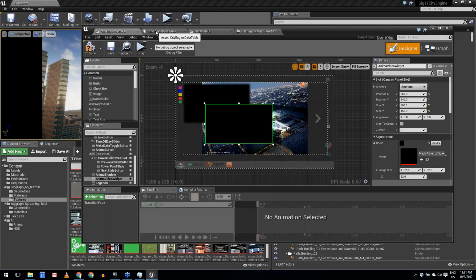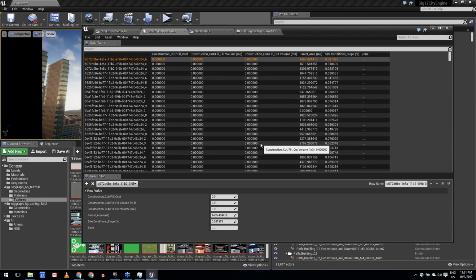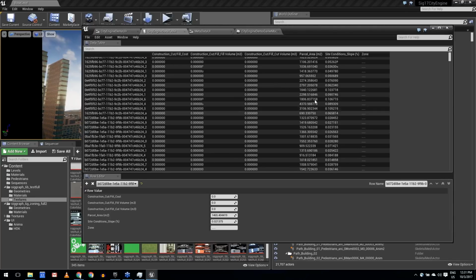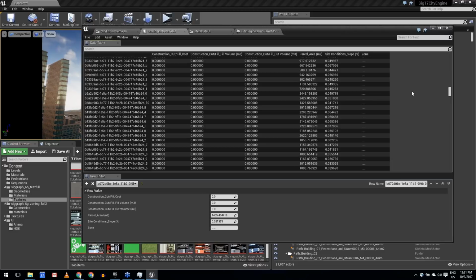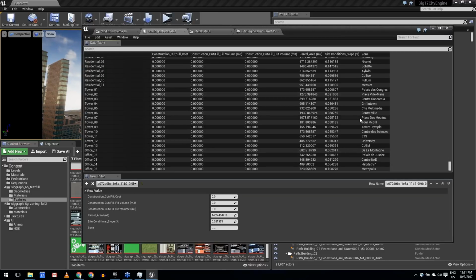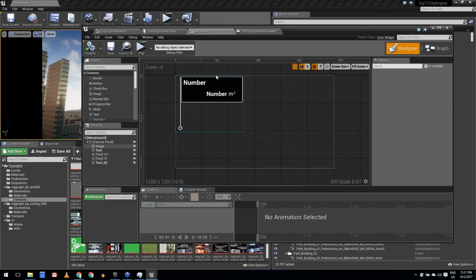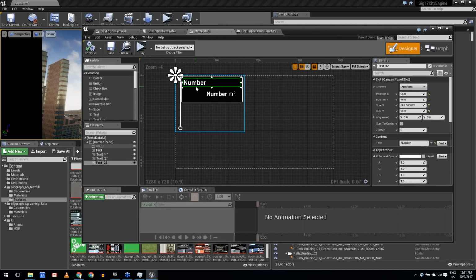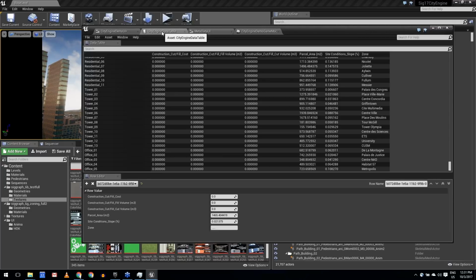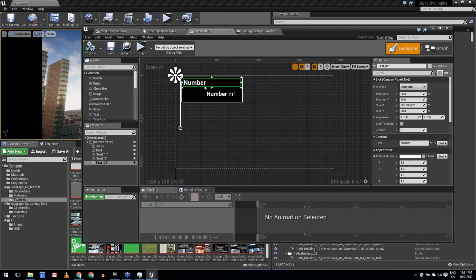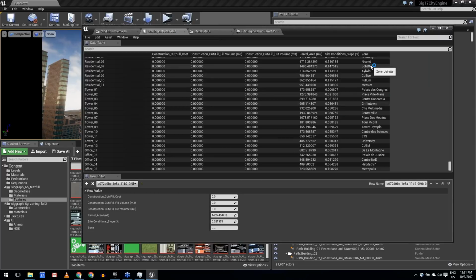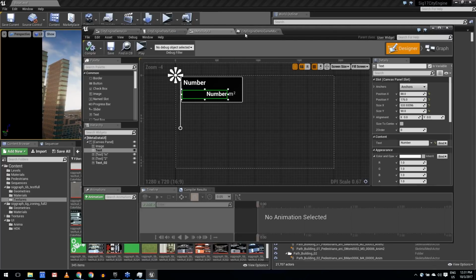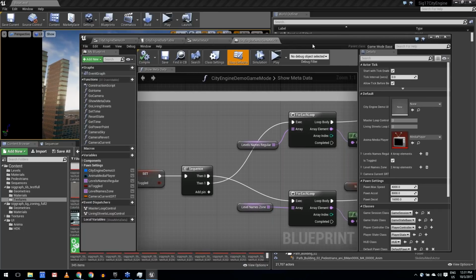The other interesting aspect is that Unreal is capable of loading Excel spreadsheets, basically. So CSV data, and we wrote some scripts to load that in, and in which you get the area as well as the names that were used in the presentation. So you don't have to hard code this into graphics. You drive the data procedurally, and how it's done is by creating a generic piece of UI like this, where you assign data fields, where you say this text here will actually look up the value contained in this column, and this text here will look up the value contained in the other column. So this is pretty much how this is all set up inside Unreal.